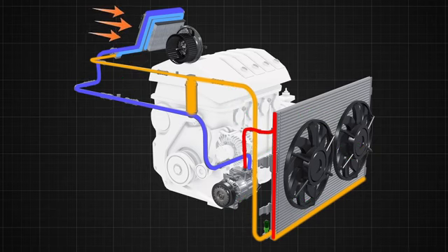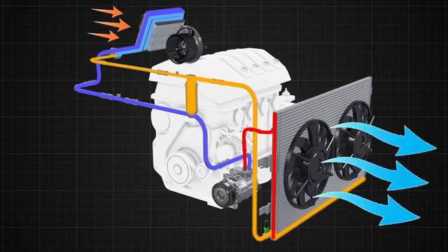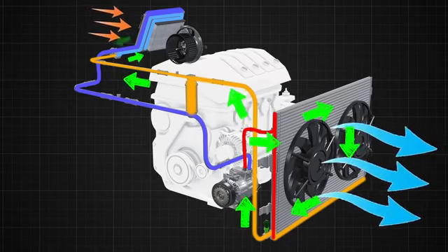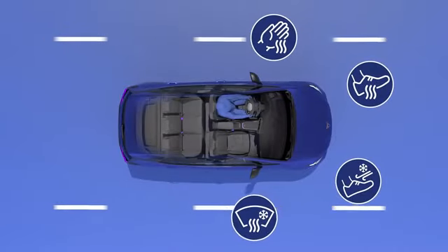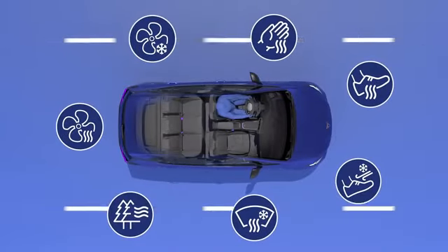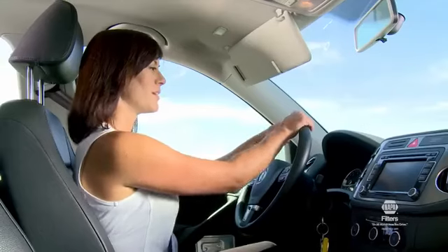with the evaporator absorbing heat from the cabin air, the condenser releasing heat to the outside air, and the expansion valve controlling the refrigerant flow between the two. This continuous cycle allows the AC system to maintain a comfortable cabin temperature and humidity level while the vehicle is in operation.